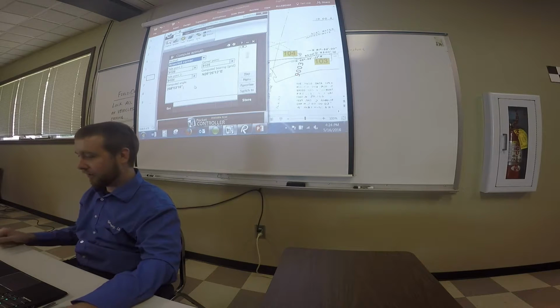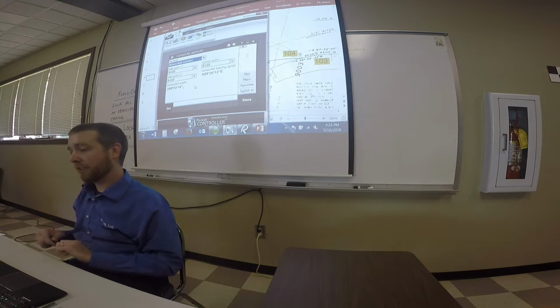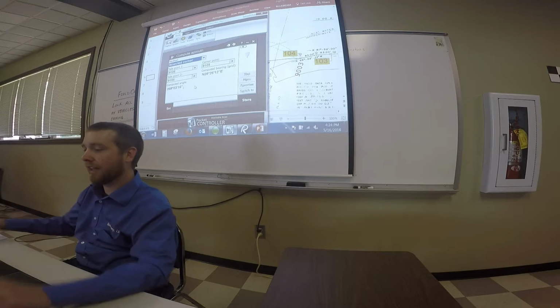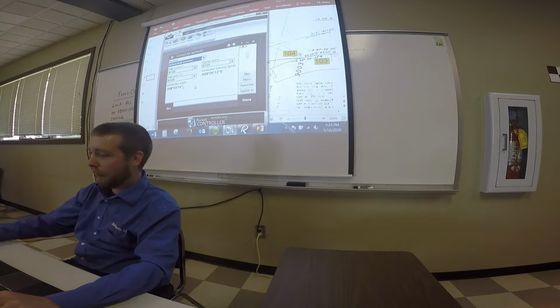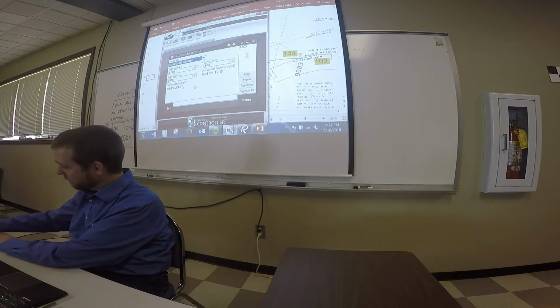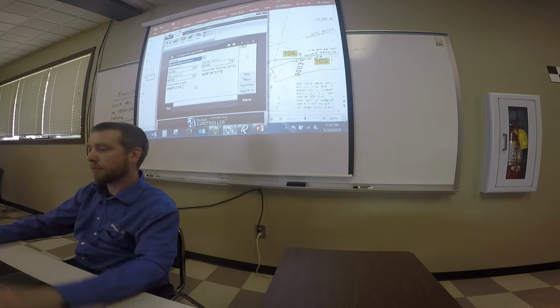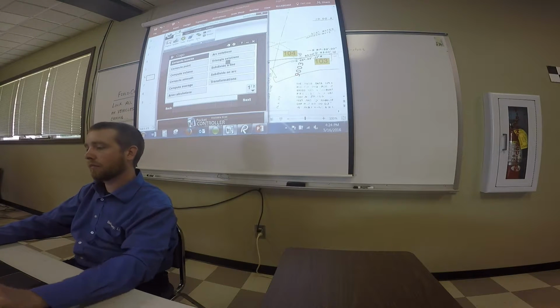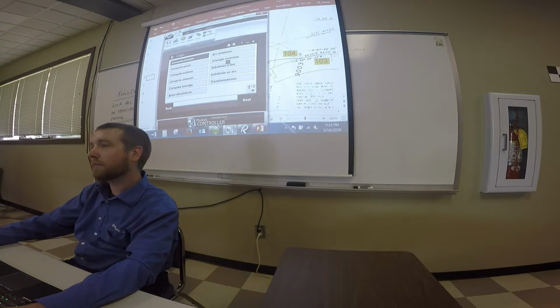Now, this is not on datum, and we didn't have to put it on datum. This is just a simpler way to find 1, maybe 2 points. You can find this angle. So if you're missing just 1 or 2 pins, it's not worth digging into a big old translate, rotate, moving a bunch of points here or there to just calculate 1 or 2 sets of coordinates. It's simpler to use angle right and distance.